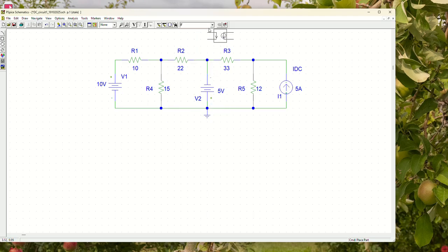Next, suppose I am selecting F. So what is F? If you see it closely, this is a dependent source, right? As you can see here, the source is a current source represented by this circle, and it is dependent on a current, because this is a current symbol, right? So this is a current dependent current source. So like this we can have various components as we require.